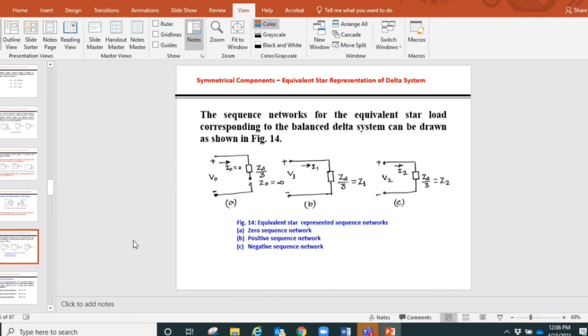Now, if I leave this lamp alone, because we can increase the frequency and stop the flickering of the lamps, but if we go to a motor, like I said, we can have a light bulb and a motor, or we can also have a transformer connected to the generator for stepping up or stepping down the voltage. So what happens to those motors and transformers when you connect them to the generator? Motors and transformers both have windings in them, either single phase or three phase, doesn't matter, and those windings represent some sort of impedance.